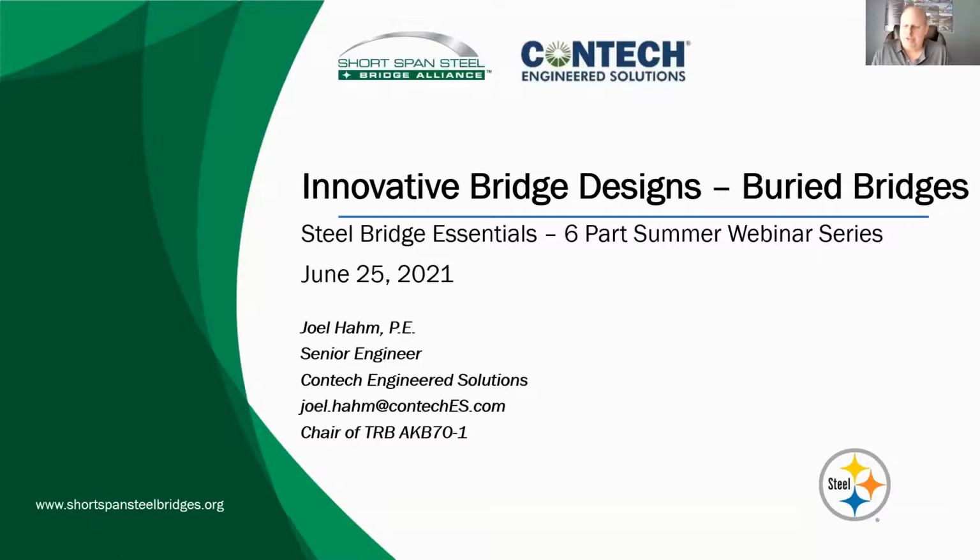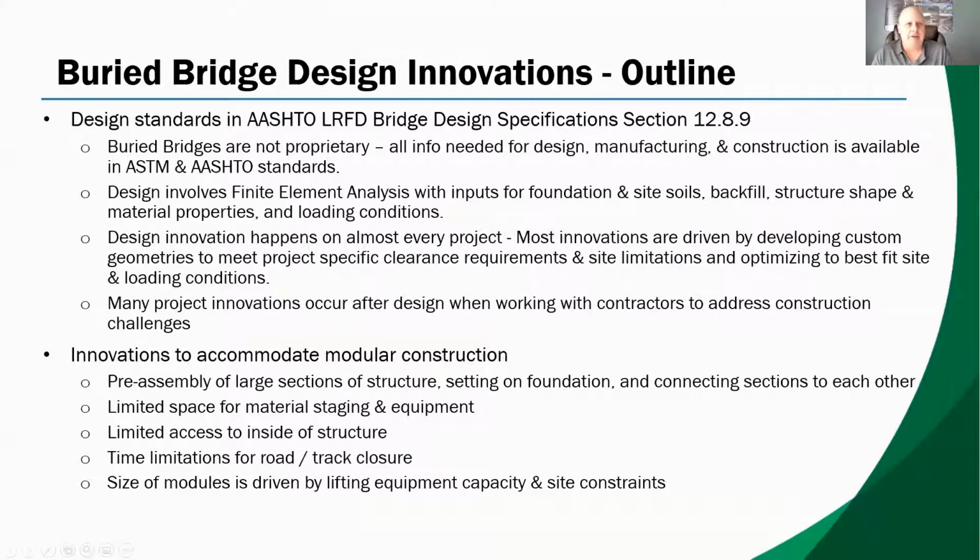So today they asked me to talk about buried bridge design innovations. Maybe a real quick review for people who don't know: the design standards for buried bridges are included in Section 12 in the AASHTO LRFD. More specifically, what I'm going to show you today is in 12.8.9, which is deep corrugated structural plate.